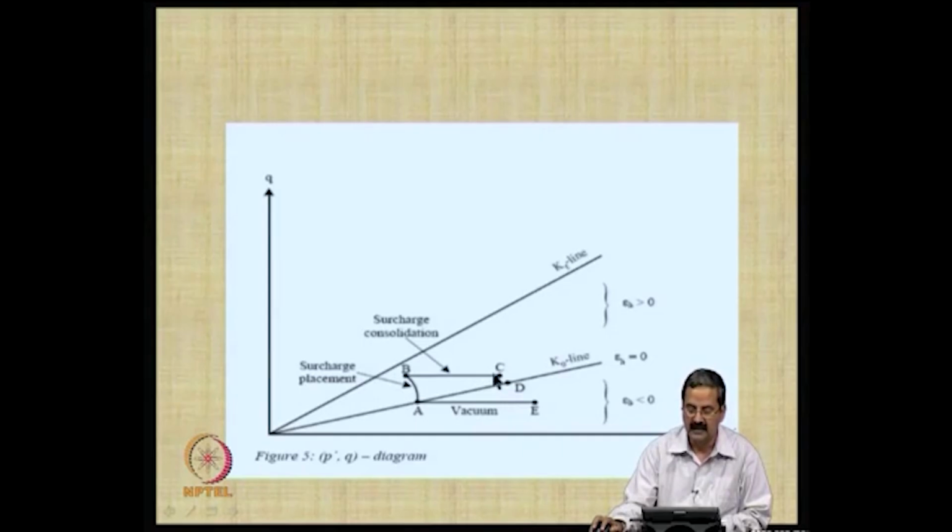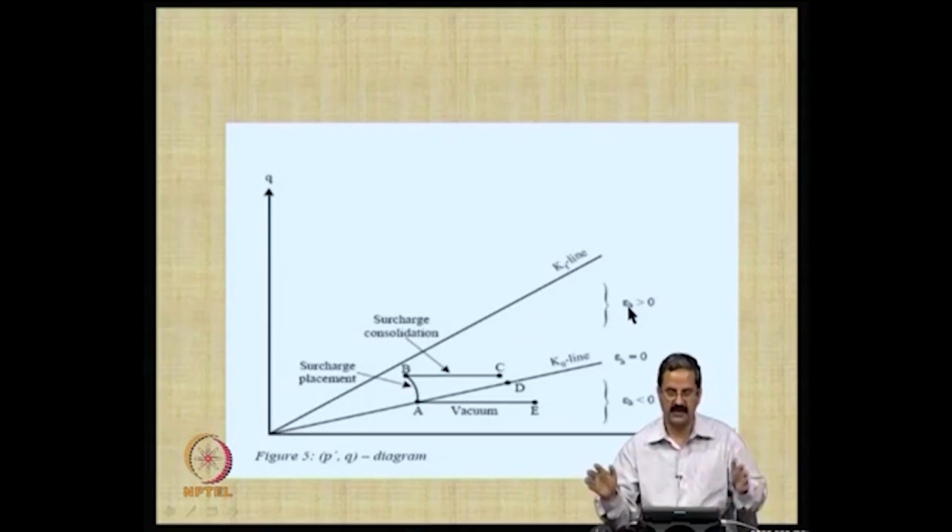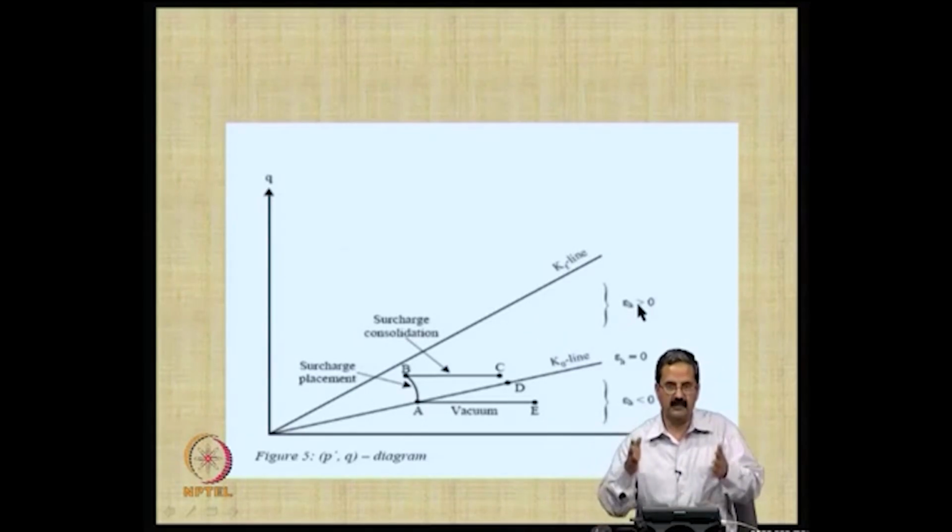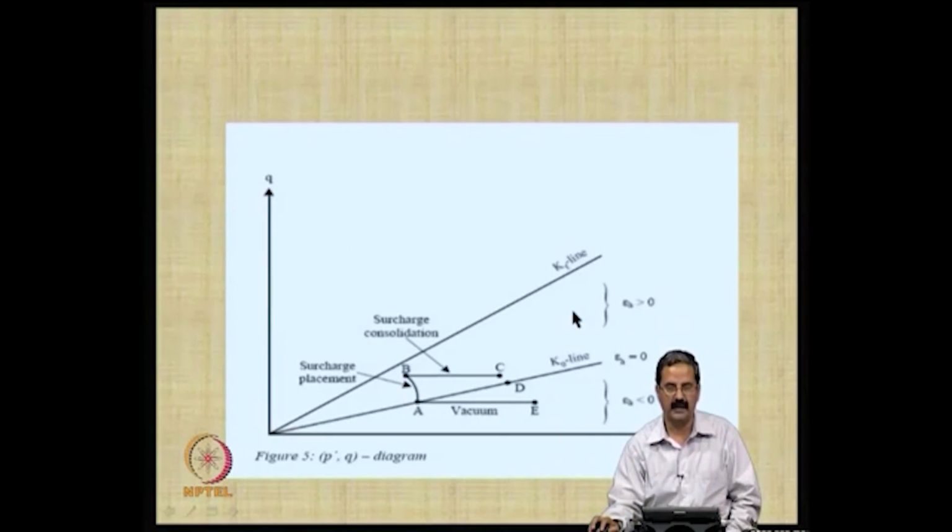You can see that there are always some horizontal strains there, because the moment the soil state is in this range, there are always some horizontal deformations that exist, but if the horizontal deformation is too much, then total collapse takes place, right. The horizontal deformation should not be too high, because it is a combination of shear and volumetric strains, and it should not lead to failure. So, you can see that this is a region at which horizontal strains are higher, and this is a region along which horizontal strains are 0, and here what is happening?